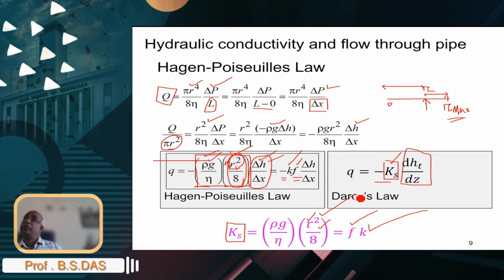But we also know from the water retention characteristic that the wetness of a soil is uniquely related to the energy content of the soil. So in other words, in an unsaturated soil, you will also see this non-linear relationship between the potential head and the conductivity, right? So whether it's the pore size, the amount of water, or the potential of soil water, all are going to be linked to this conductivity function through this sort of non-linear relationship between the conductivity and permeabilities, right? So it's the intrinsic permeability that will change, right?